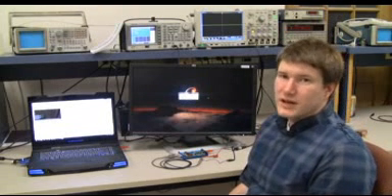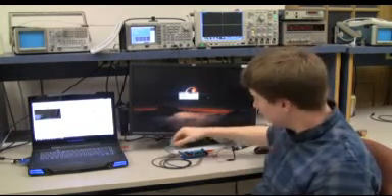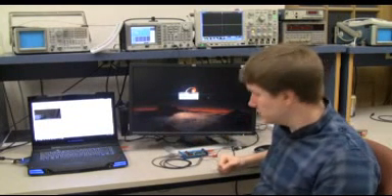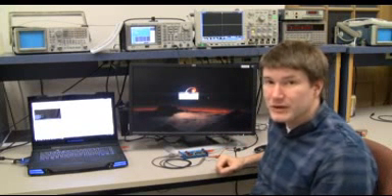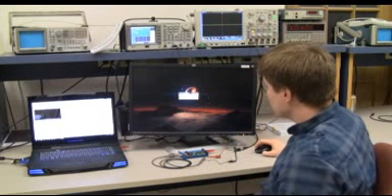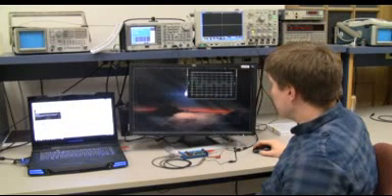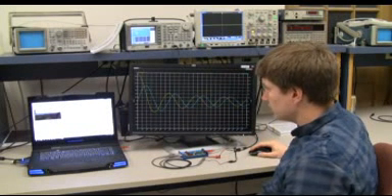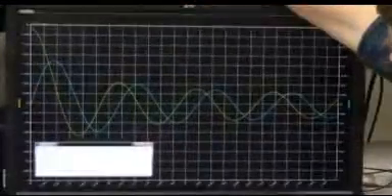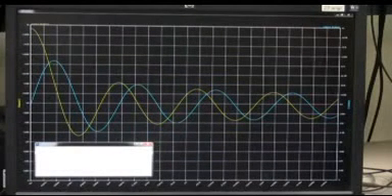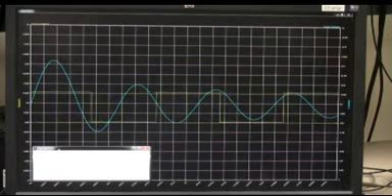Alright, we're going to demonstrate the operation of the oscilloscope. You can see the device is connected to the computer via USB cord. And to channel 1 we have a 10x probe where we are measuring a 1 kHz square wave with a 20 volt amplitude. To launch the oscilloscope we click the launch button, and when we get all the windows in view, we can turn the function generator on and click enable on the channel 1 view.